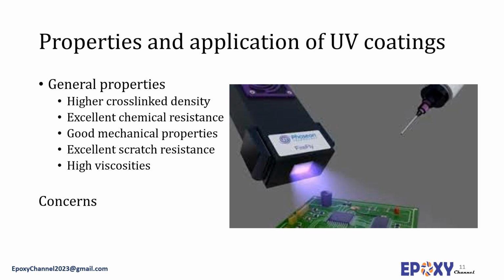A technique called dual cure can be employed to overcome the problem of application on three-dimensional objects. In this technique, cross-linking occurs through another supplementary reaction in addition to the UV curing. However, most dual cure systems are no longer solvent-free.